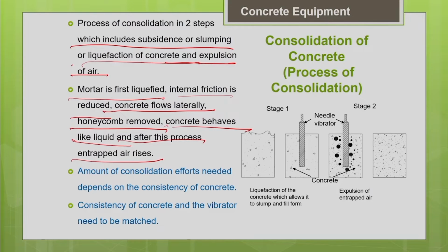You can see this in the picture also. In stage 1, what is happening? Your concrete is getting leveled. You can see the subsidence is happening, so it completely fills your formwork. After that, you can see that your air will rise to the top surface. So the first thing that is happening is liquefaction.